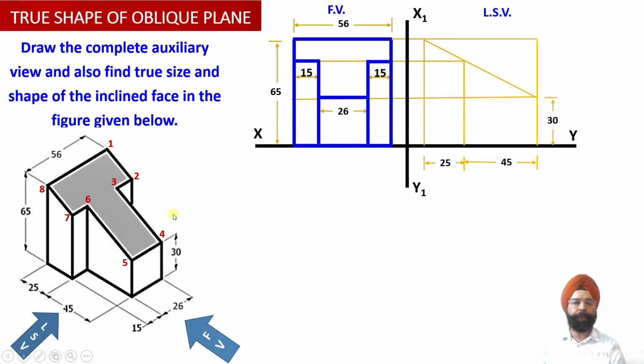So we are able to obtain the true shape of this surface onto the vertical plane, right? So this is true shape, this is true shape, and this surface is also true shape. So now we are left with this T cross section, which is an apparent shape or a foreshortened projection of this T-shaped section surface which is lying on the top of the solid.